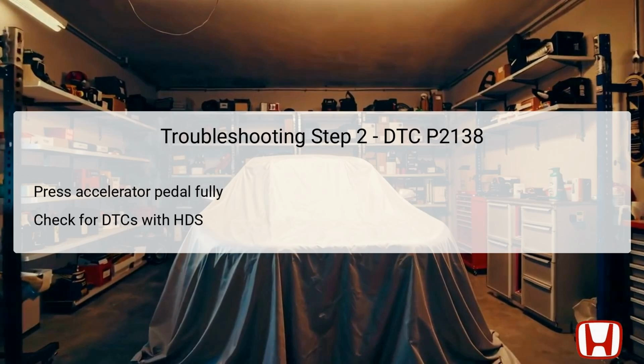If the code appears, this indicates that the malfunction is persistent and requires further investigation. Conversely, if the code does not show up, this may suggest an intermittent failure reported previously, prompting the technician to check for poor connections or loose terminals.